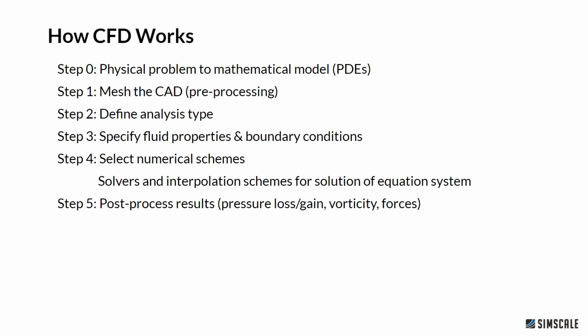Step 5 is of course post-processing the results. That means we're trying to make sense of what we actually calculated. For example, we will have a look at pressure loss, gain, vorticity, forces and so on. But it really depends on your simulation and the quantities that you are interested in.